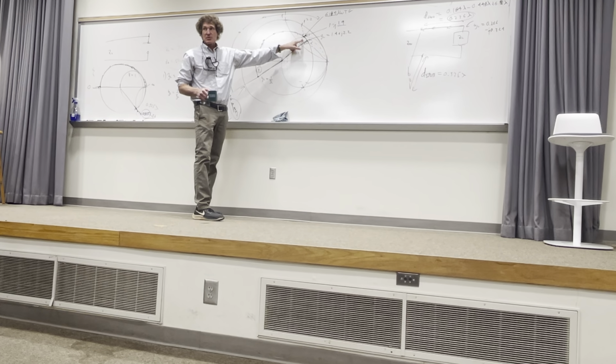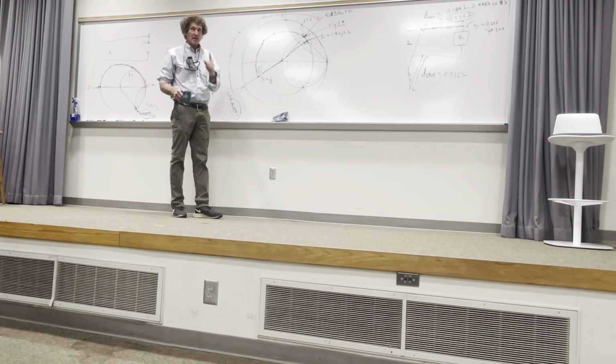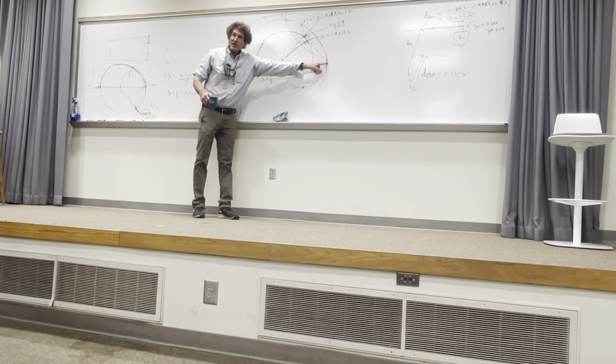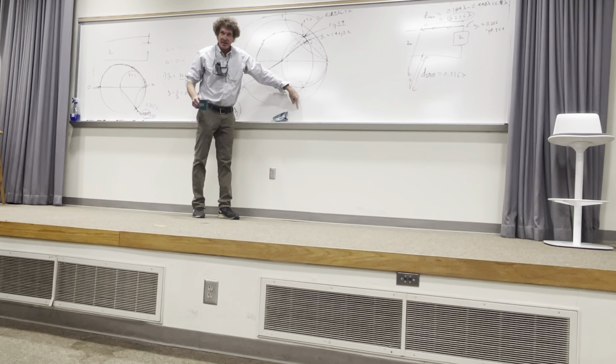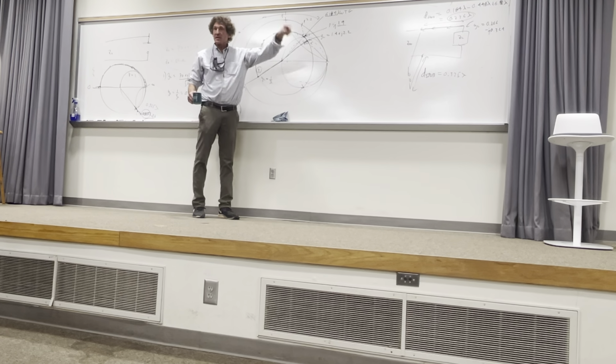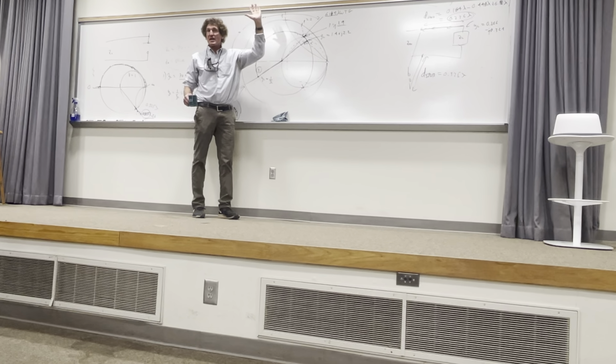Now, if it's a short circuit stub, where do we start? Right here, right? And now our short circuit stub length is going to be much less. Y'all follow me on that? It's going to be a quarter wavelength less. Make sure you see that in your mind.